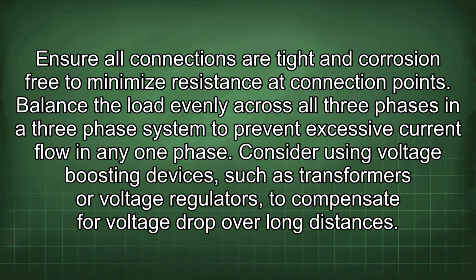Balance the load evenly across all three phases in a three-phase system to prevent excessive current flow in any one phase. Consider using voltage-boosting devices such as transformers or voltage regulators to compensate for voltage drop over long distances.